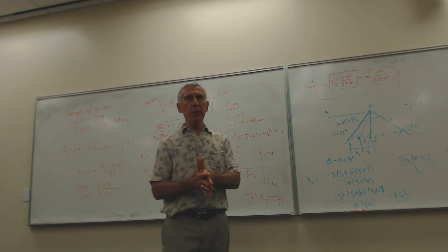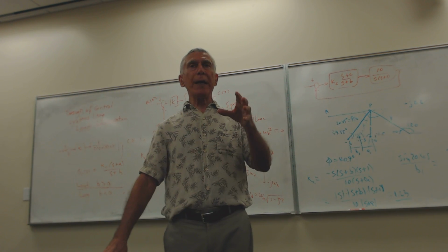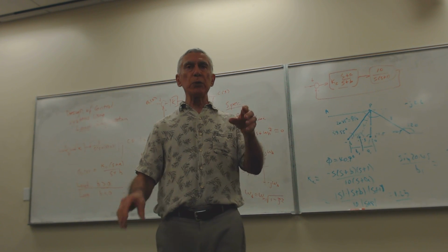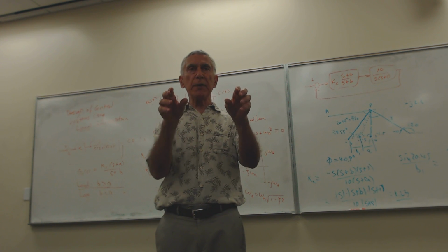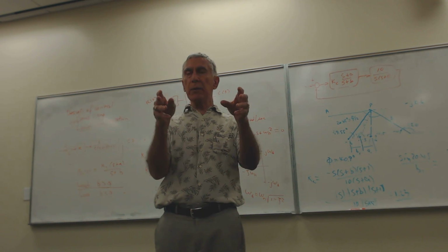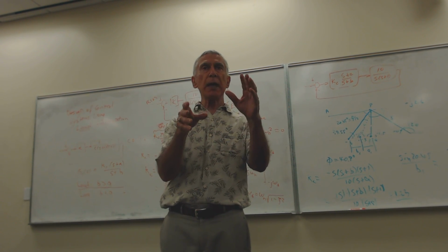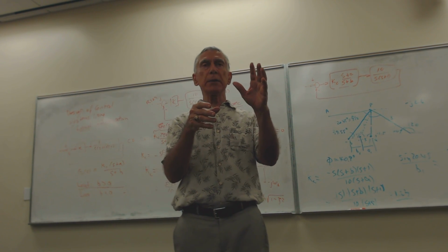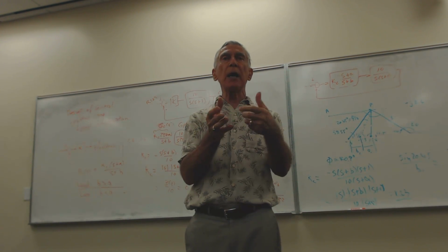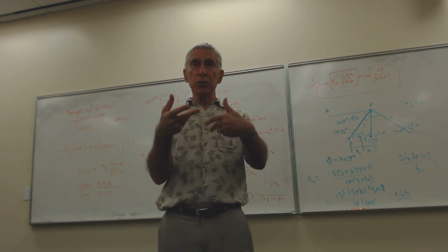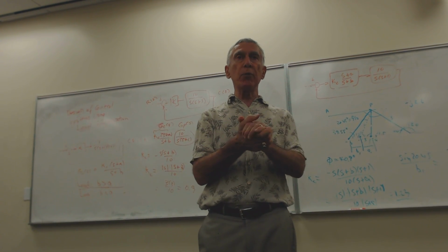And like I say, they're really good. You should be aware that there are an infinite number of possible solutions. Remember that you can adjust the values of the A and B, the pole and zero locations of the lead compensator, such that the positive phase angle contribution that the lead compensator has to contribute is equal to, in this example, 40.9.